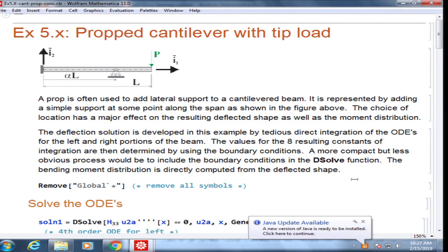If the load was upwards, you would put plus P. If you consider shear force on the left side of the slice, then this is positive downwards. So positive downwards, positive sign, minus P, equals 0, because P is on the right side of the slice. You are doing equilibrium on the slice.